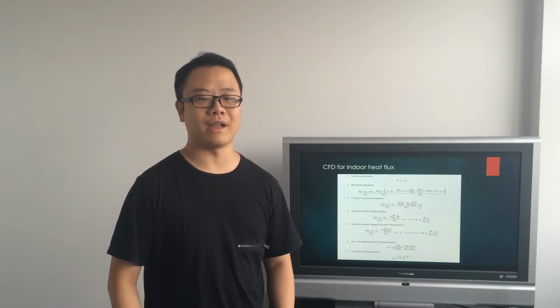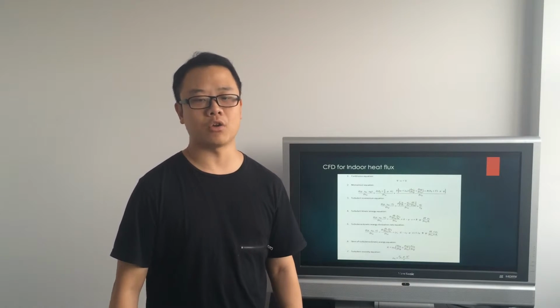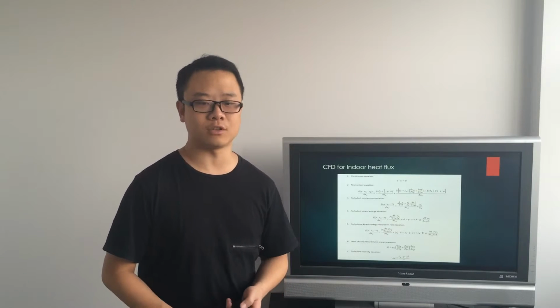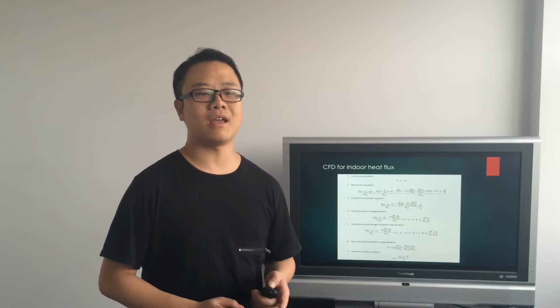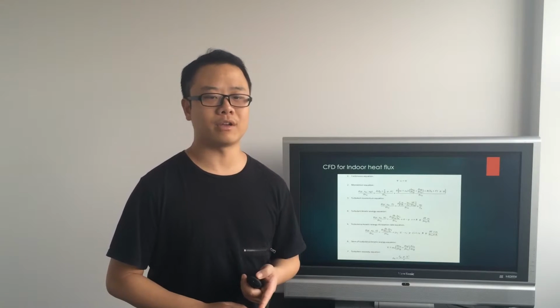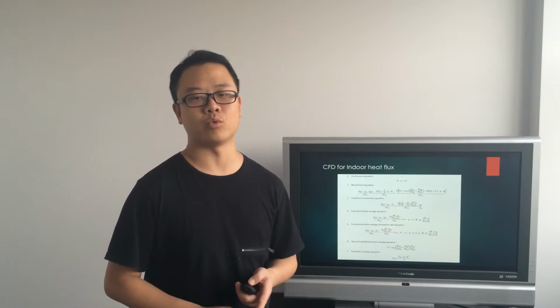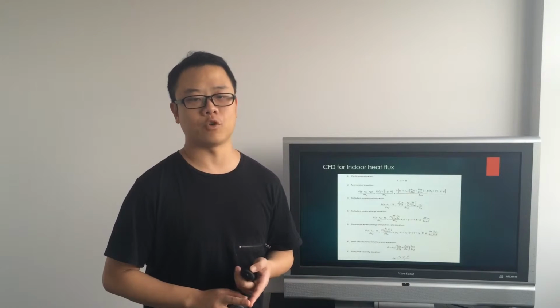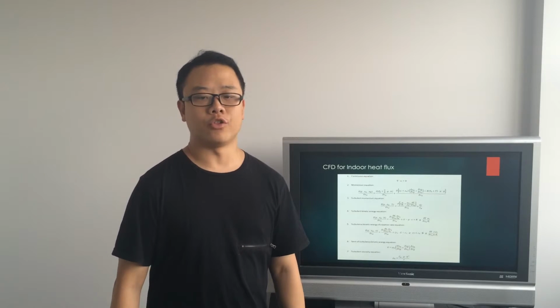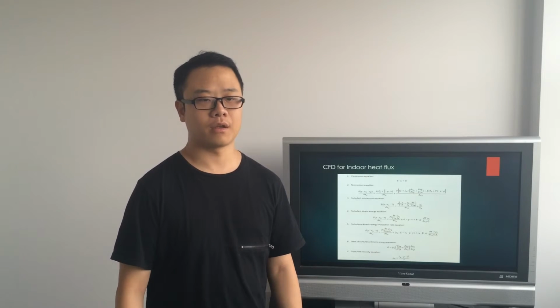C3 has no exact value. It can be calculated by the following equation: C3 = tanh(Up/Un), where tanh is the hyperbolic tangent, Up means the flow component velocity parallel to the gravity direction, and Un means the flow component velocity normal to the gravity direction.